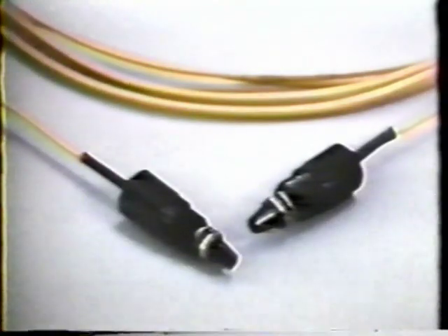Let's look at two different types of light guide connectors which have been developed to minimize these problems: the single fiber biconical connector and the multi-fiber ribbon array connector. First, let's examine the biconical connector, which is used primarily on light guide patch cords and jumper cables. The components include two plastic conical plugs at the ends of the fibers we wish to join, and a biconical sleeve, which accepts and properly aligns the plugs.